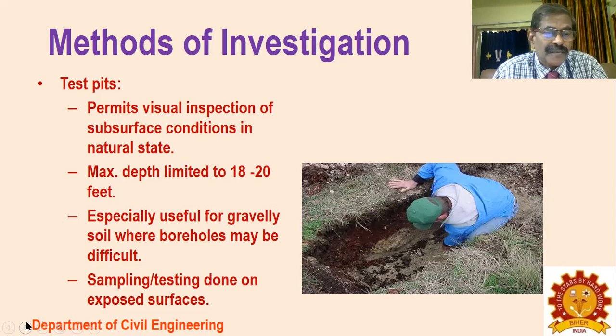1 to 2 story height of the building, given 20 feet. So to that extent, you can dig a pit and understand how the soil is there. It's an inspection pit, especially useful for gravelly soil where the boreholes may be difficult. So opening the surface and then understanding is very much useful.